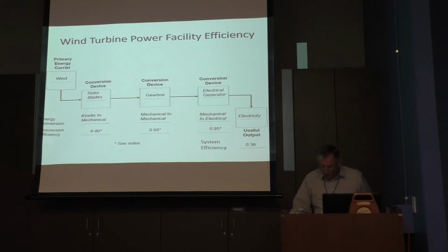Now the efficiency of gears with high gear ratios ranges from 75 to 95%. And if we use a typical gearbox efficiency of 85%, together with a maximum permanent magnet generator efficiency of 95%, then the system would have an efficiency of about 32%. In this case, though, I've used the maximum gearbox efficiency of 95%. Then the maximum system efficiency is about 36%.